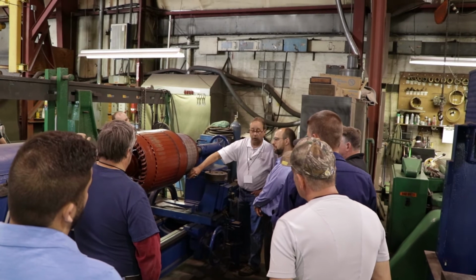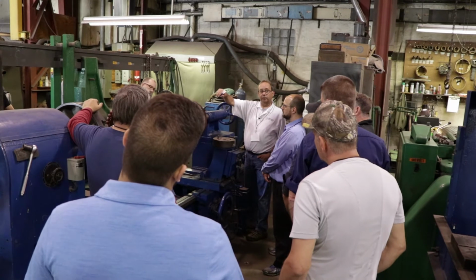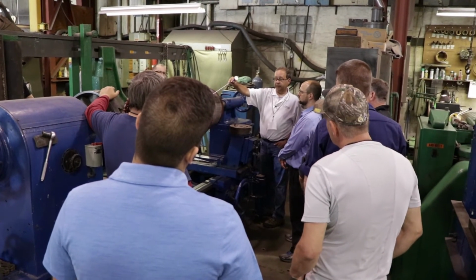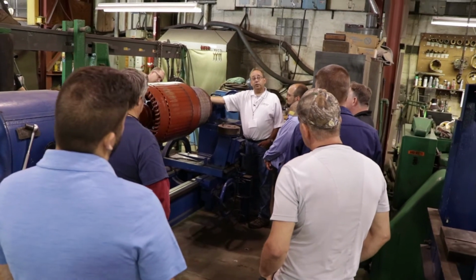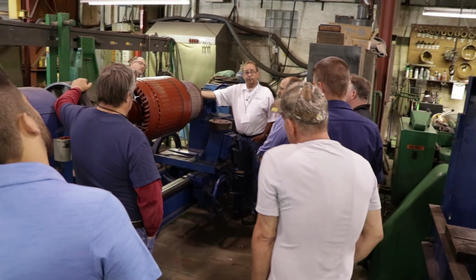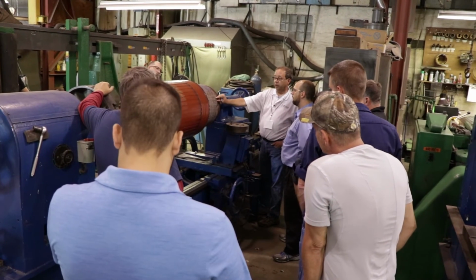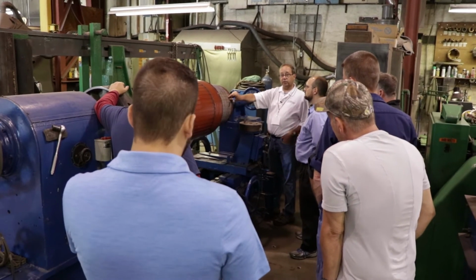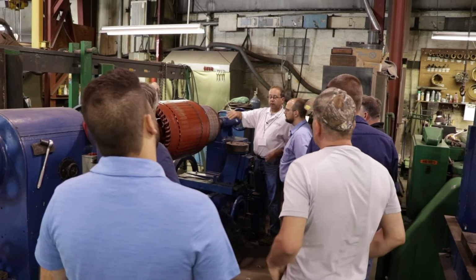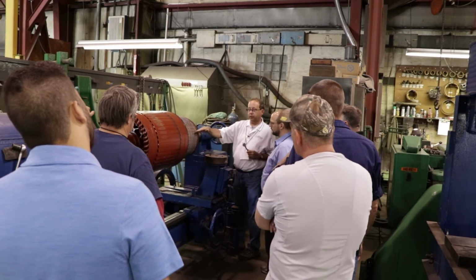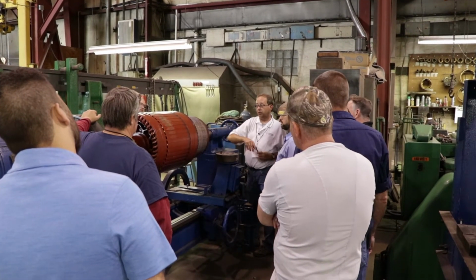The opposite end of the coil will come out on the opposite side, which is directly opposite of this one. So if this end is connected to this end of the coil, then the other one is actually one past halfway on the comm. Now the brushes are going to ride right on top of this, generally covering at least 2 or 3 segments. So as this is rotating, it's commutating voltage to the appropriate coil as it's positioned in this armature.